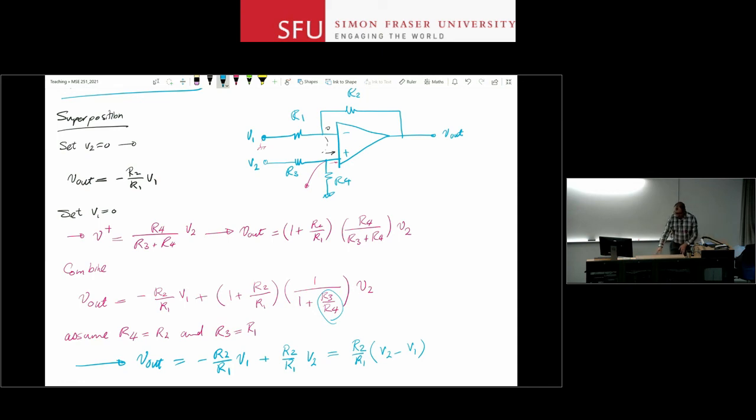We talk about some of them later on, but basically with an OpAmp you have all the tools you need for analog signal processing. I'll talk about making integrators and differentiators in a second, and with those circuits you can solve differential equations in the analog domain. So you have an integrator that takes the integral of the signal. You can do that many times. You can have 5 integrations of that signal.